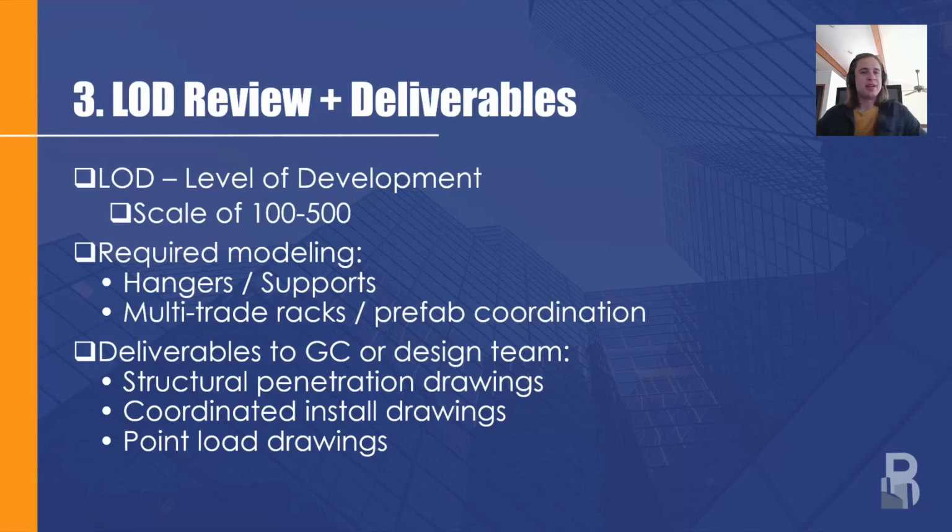The other thing is, what deliverables does the GC require within this coordination process? Some standards for these deliverables are structural penetration drawings. These often get brought into a combined set of drawings between all of the MEP trades and submitted to the structural engineer.